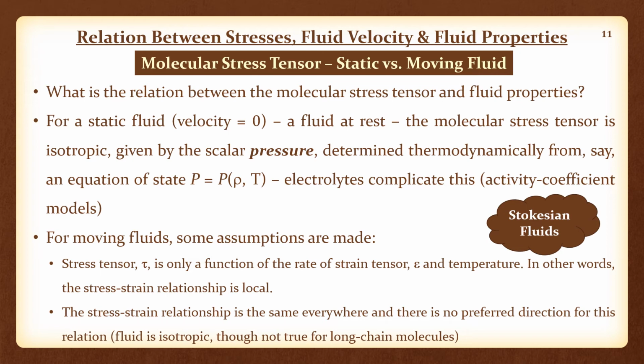So for a static fluid, the molecular stress tensor collapses into a scalar called pressure, and that pressure can be related to the fluid properties by way of some thermodynamic model for that fluid. Typically, as an example, it is an equation of state.